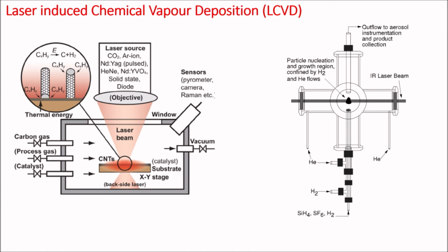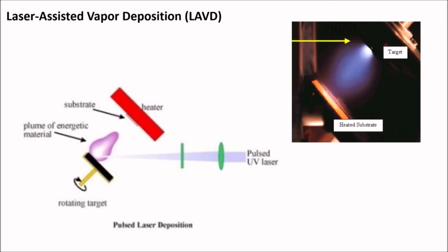Another example of laser assisted vapor deposition involves the laser decomposition of the precursor gaseous molecules to produce the desired materials. Laser assisted processes have also been used for depositing thin films and nanoparticles in physical vapor deposition schemes. For example, the ablation of a solid target is possible with lasers, where the ablated materials are deposited onto a substrate.